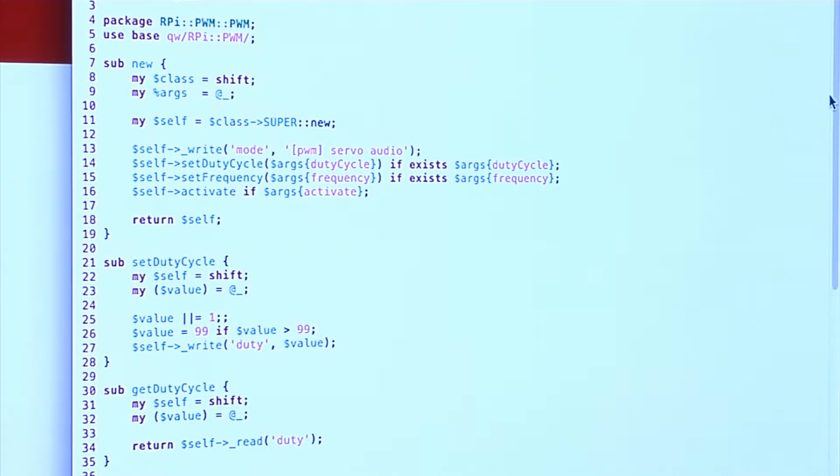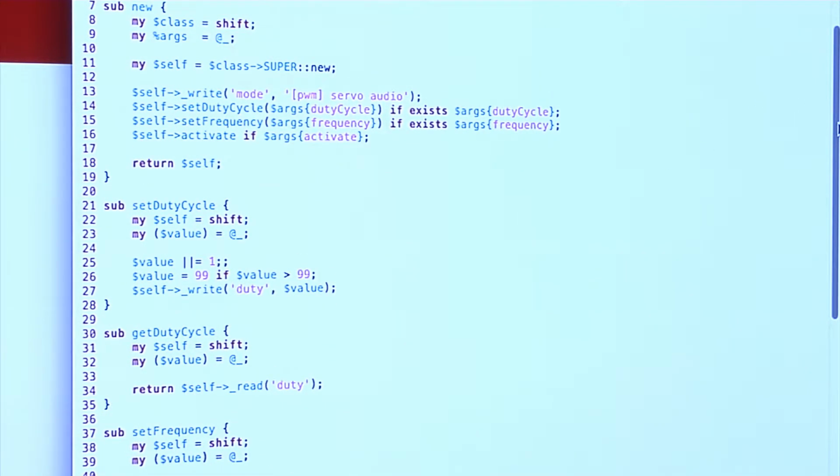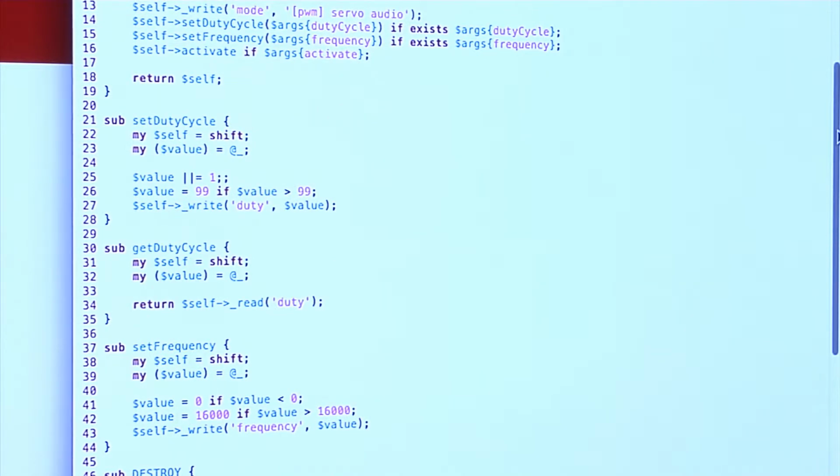This is the first class. This is the one that actually does the pulse width modulation. We have methods here to set the duty cycle and the frequency. Those are the ones we're most concerned with. As I said, I'm setting the frequency to 100 hertz, so your eyes can't detect the flicker. And then I'm going to vary the duty cycle, and you'll be able to see the bulb glow and not glow, or go on and off slowly rather than just like it was doing before.